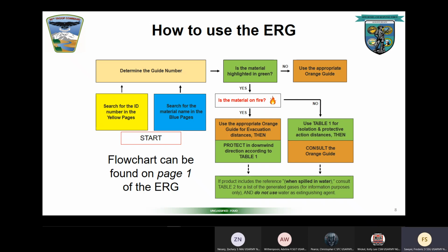It says for a highway tank truck or trailer, since it's so large, you first isolate in all directions for 600 meters or 2,000 feet. So it's a pretty big evacuation area. Chlorine is pretty nasty. So that's the first thing you want to do. Immediately you see 60 and you get everybody at least 60 meters away.